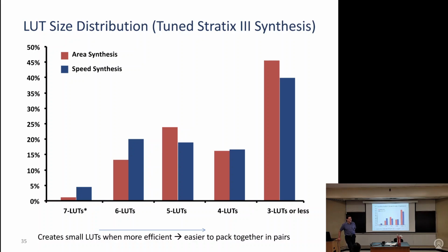I have to use my LUTs. I don't want to use my LUTs. So there actually are academic papers where they say, could we just use the muxes and crossbars in the routing to do this function? And they show you can, but you essentially have to add paths from other routing, right, to bypass the SRAM cells and start controlling some of the routing muxes dynamically.